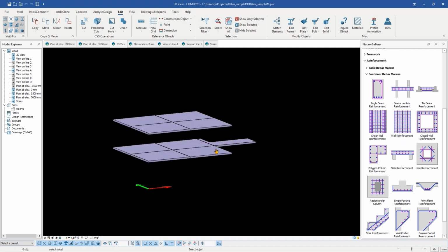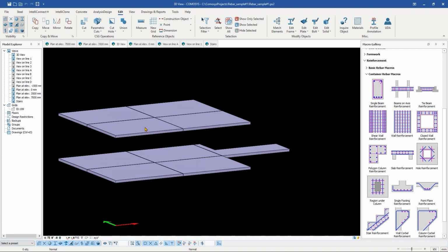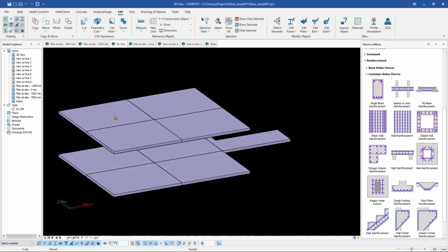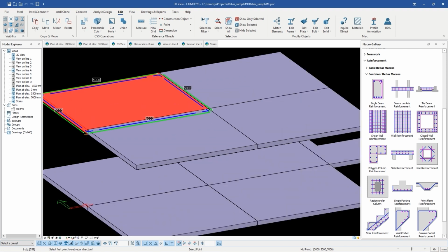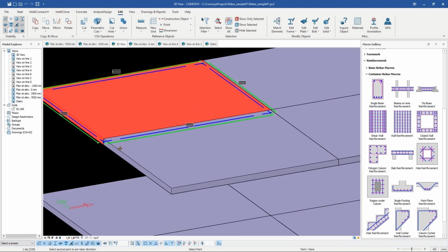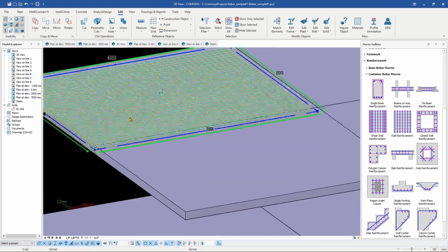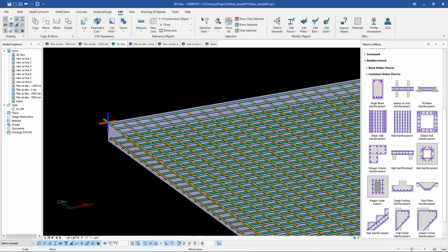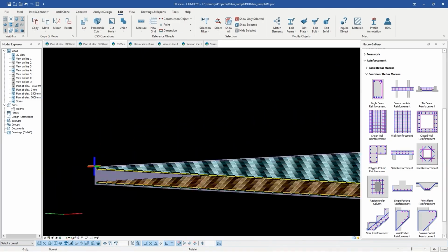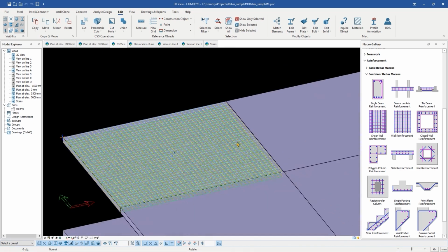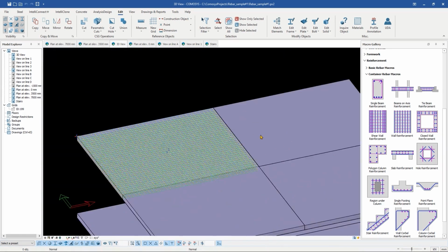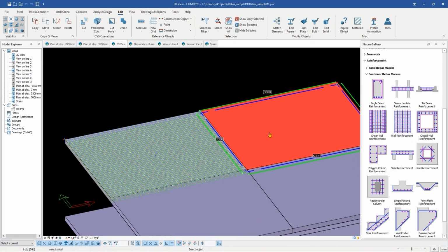User need to click on Apply button after finishing the entry of rebar data. Now, just tap on Slab Reinforcement macro and select Slab, then select any 2 points for main reinforcement direction. As we can see, reinforcement for slab is created. User can repeat the same process, or use Copy to another object command to create rebars for the rest of the slabs in the model.